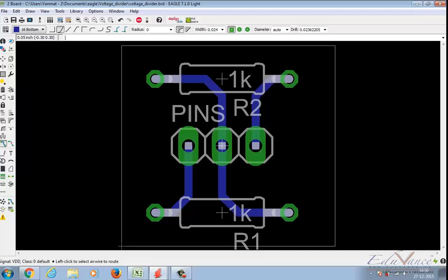Okay, so we are done. Now you can still use the show tool and click on the pads. These green circles or the green areas are called component pads. This is where you will actually be soldering your component leads. Select a pad and see if it's connected. So this had to be connected here. The green highlight will indicate that yes, the connection is achieved.